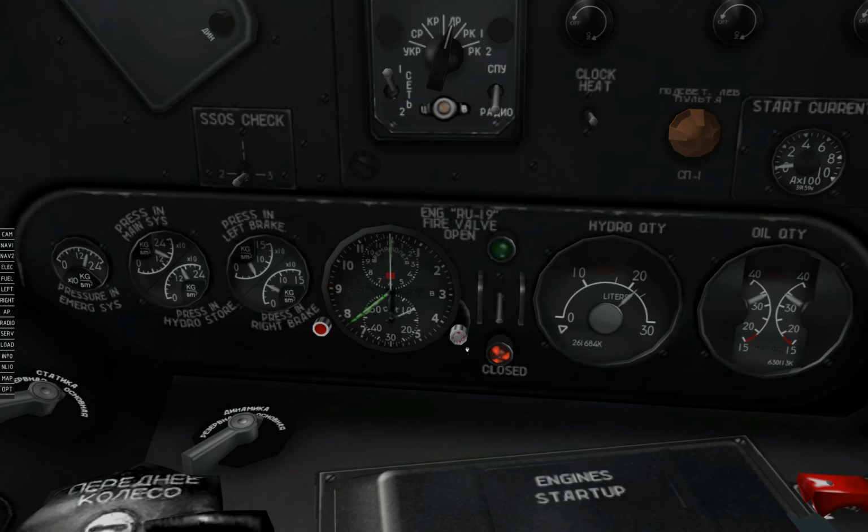The only difference is that this clock has no color flag indicator in it because the needle moves fast enough to be able to tell what the status of the clock is at a glance. Please note that this clock is synchronized with an identical clock on the right-hand side instrument panel, which is in the first officer's area, and that will be covered in a future tutorial.